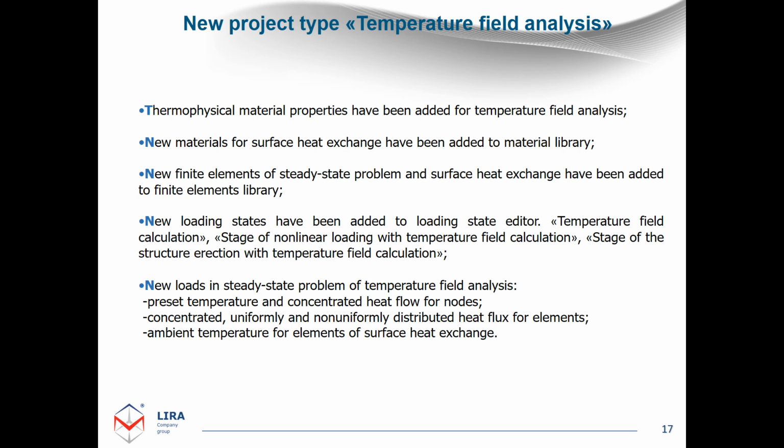Let's now move on to the next main innovation. It's a new problem type called temperature field analysis. While working on a steady-state thermal problem, we've implemented the following: new thermophysical material properties, and new types of materials were added to material library, so you can assign them to elements of surface heat exchange.